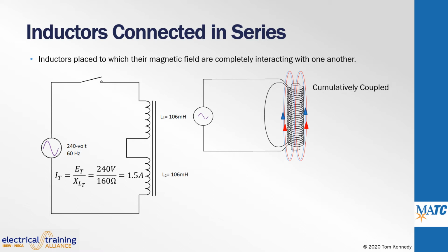The total inductance in the previous example was the sum total of the inductance connected in series. This is the foundation of calculating the total inductance, but the factor of 2m is now added to account for the coupling of the two additive magnetic fields. Without going into detail, calculating magnetic field strengths in the interaction takes a bit of calculus, but an approximation formula for m can be used, where k is a constant for the percent of the magnetic field that interacts between the two coils.